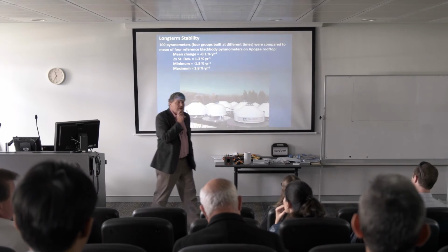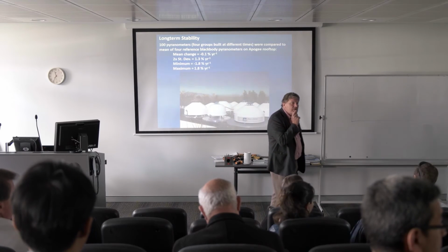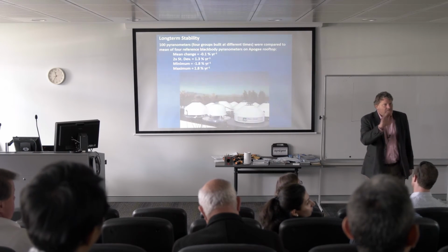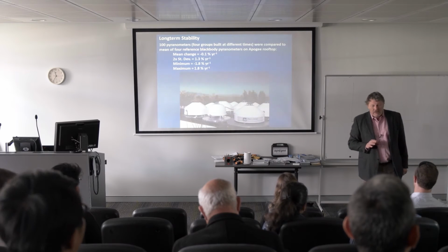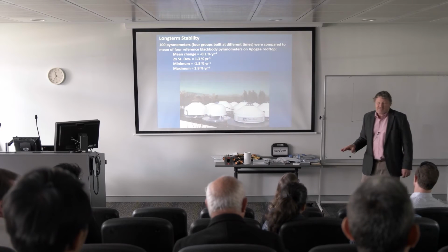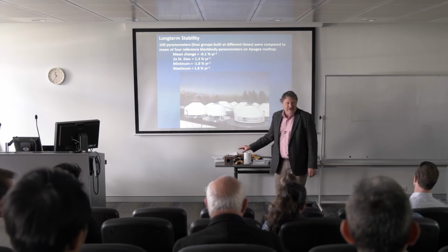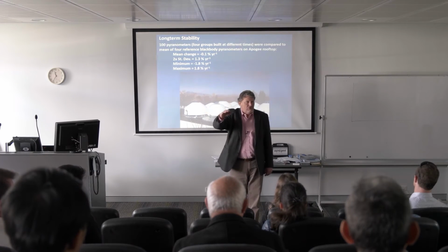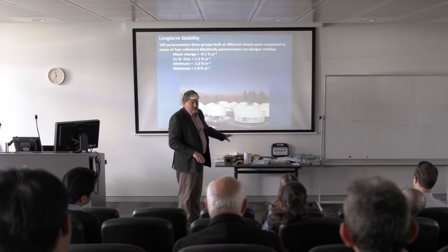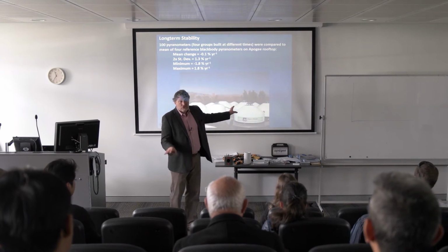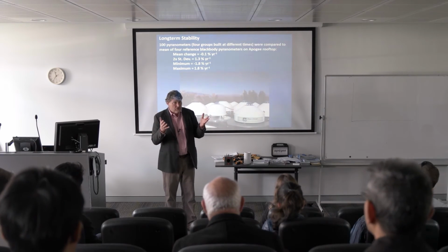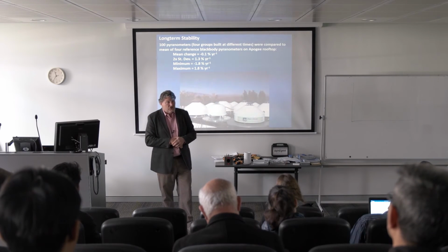Yes? Do you get any oversampling in growth cabinets where it's measuring artificial light? Yeah, did you say what happens with artificial light? Do you get any oversampling? You bet you do. These are calibrated for sunlight based on that first slide. Lots of people put them under electric lights, which have a very different spectra than sunlight. So silicon pyranometers can be way off, with 50% errors under electric lights because of the change in the spectra.